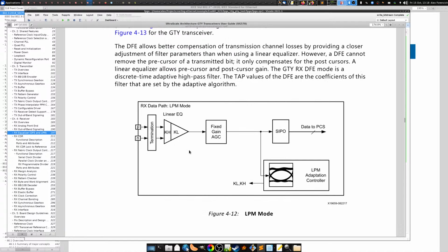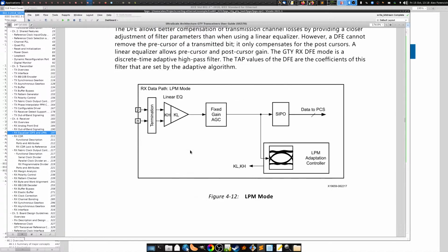The equalizer is responsible for attempting to improve the signal quality on the link. So with these really high-speed connections, the situation that you run into primarily is high-frequency loss. There are a few other effects as well, like impedance discontinuities, but for the most part, the real killer is the high-frequency loss. Where is all of that high-frequency information in the input waveform? It's all in the edges. If you have a sharp edge, that indicates you have a lot of high-frequency information there.